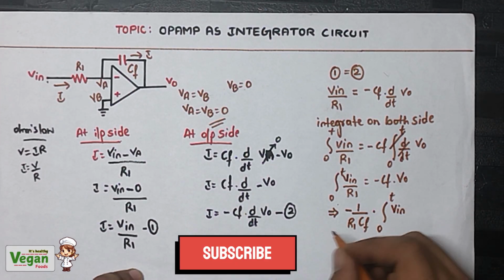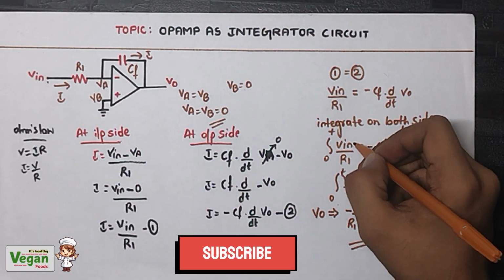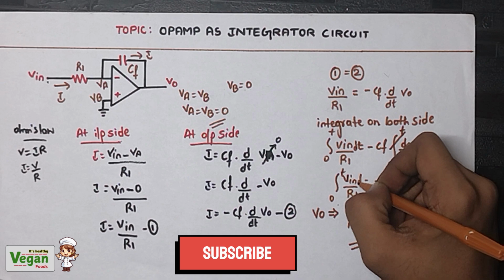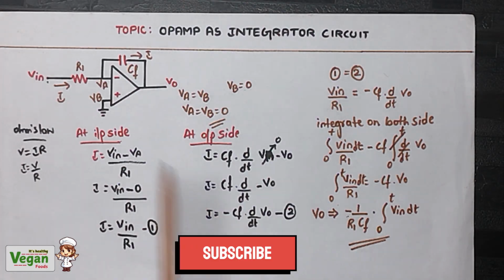R1 is constant, so we took it outside, Vin into dt. I forgot to write dt right here, so you write dt. Therefore the output voltage Vout is the integration of the input voltage. The output voltage is the integration of the input voltage, and the negative symbol shows that the input is given to the negative terminal of the operational amplifier.